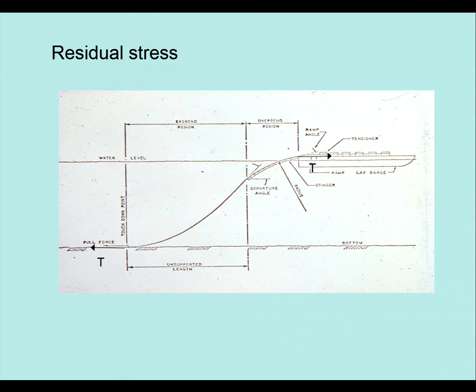What's the stress in here? This is in air, so forget about atmospheric pressure because it's so small. So I've now got a mass of this pipe acting down. Its weight equals its mass times g, and I divide that by its cross-sectional area, then I'm going to look at the stress.